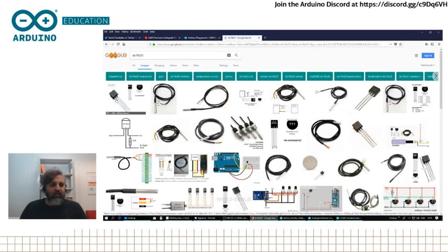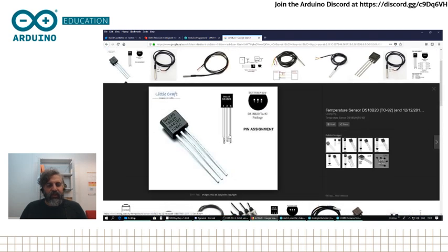And here you see this is basic information about the sensor. It has ground, signal, and power. If you look at it, it's the actual opposite polarity than the one that you saw. So it's very important that you check this out.